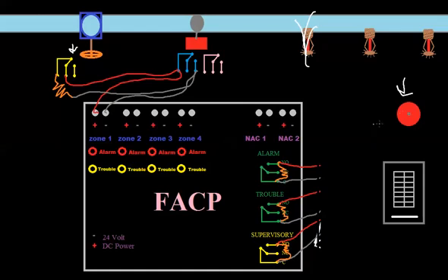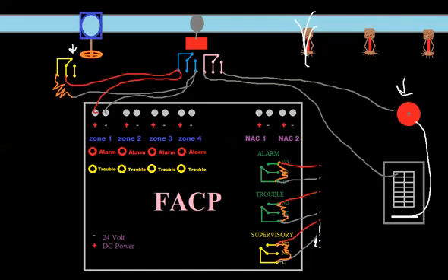It's going to work just like a light switch or just like any of our relays. We're going to take neutral out of our neutral bar, go right to our bell. We're going to take the hot circuit from whatever open circuit breaker we have. So the line comes into the breaker box and then it distributes it. And we're going to take our hot to common, and then we're going to come normally open to this bell. So when this switch activates, when the water flow activates, now our current can flow to the bell.